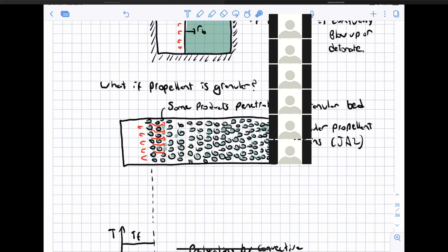And so if we were to treat this as a closed volume and ignite it from the end, what you would see is a completely different dynamic than you do for a piece of solid propellant, where it's just one large propellant grain. And for these gun systems, these could be grains of, say, JA2 or whatever modern double base propellant is used in the big guns.